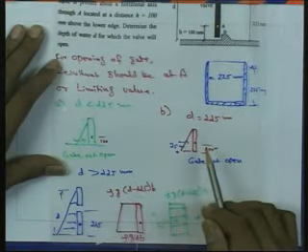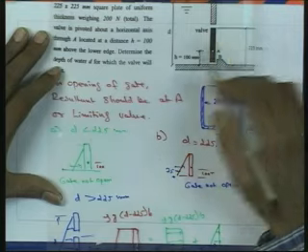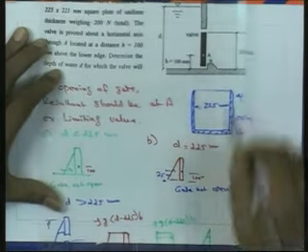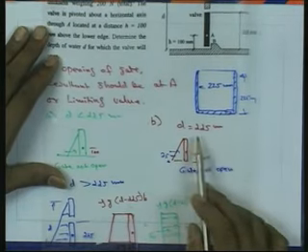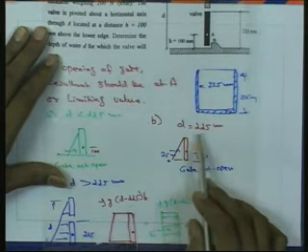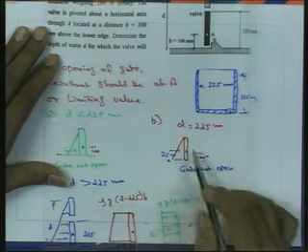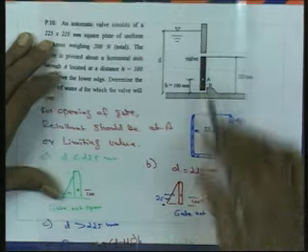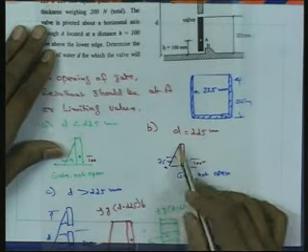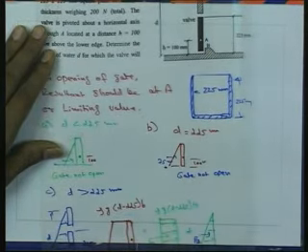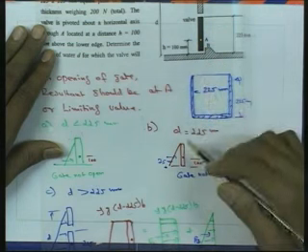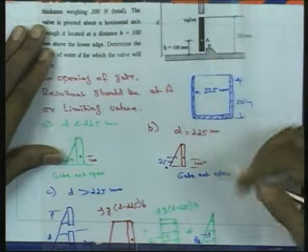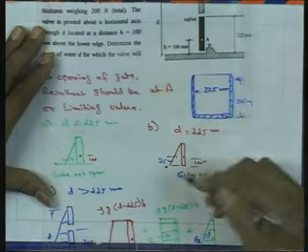Then the second case we will consider is when the upstream depth is equal to the downstream depth. So, D is equal to 225 millimeter. Here the pressure distribution with respect to the gate will be like this, and we know the center of pressure, for this vertical surface, will be D by 3 from the bottom.